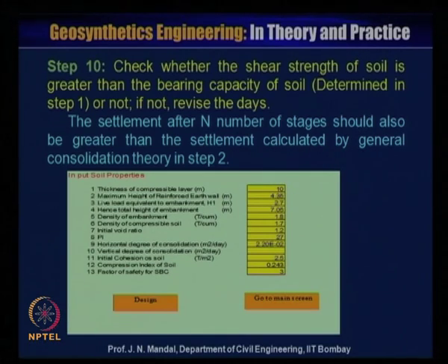Here the input soil properties are given. The thickness of the compressible soil layer is 10 meter, the maximum height of the reinforced earth wall is 4.35 meter, live load equivalent to embankment is 2.7 meter, then total height of the embankment is 7.04 meter.